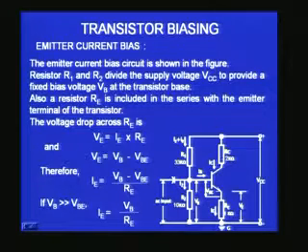So now let us find out what is the voltage VE at the emitter junction, what is the voltage at the collector point, and what is the voltage VB. If I know all of VE, VB, VC and IB, IC and IE, I have made everything ready for the biasing scheme. Now we know what is VE. Most of the application here is a simple concept of Ohm's law. That is what we are going to apply everywhere here.